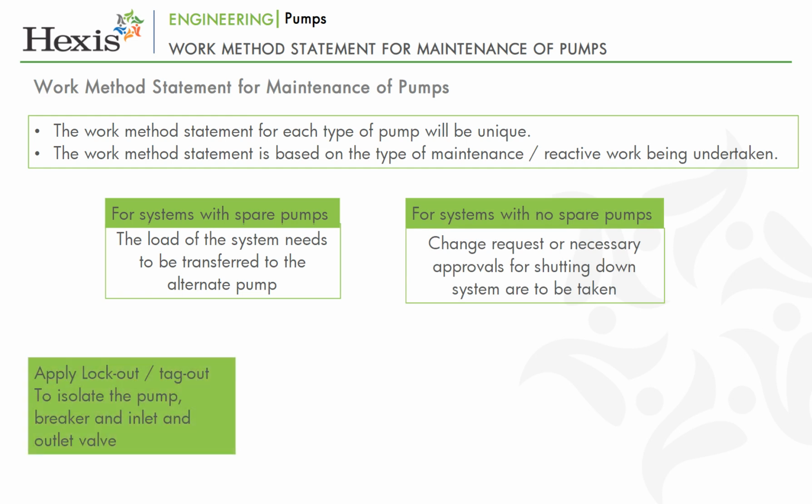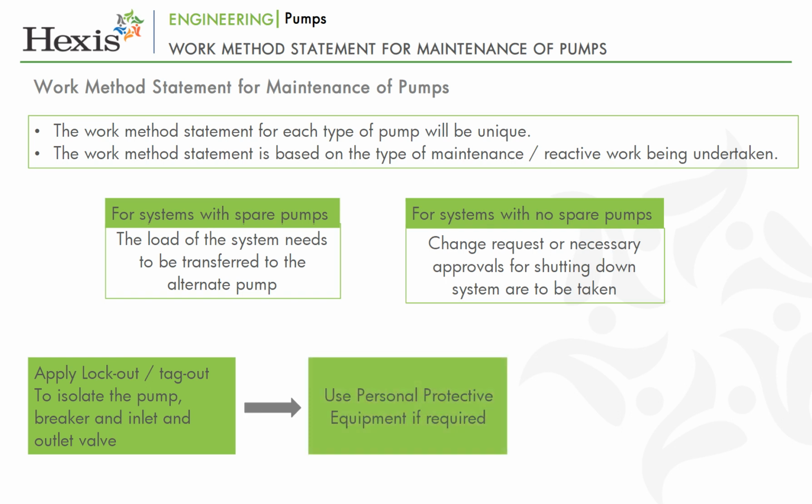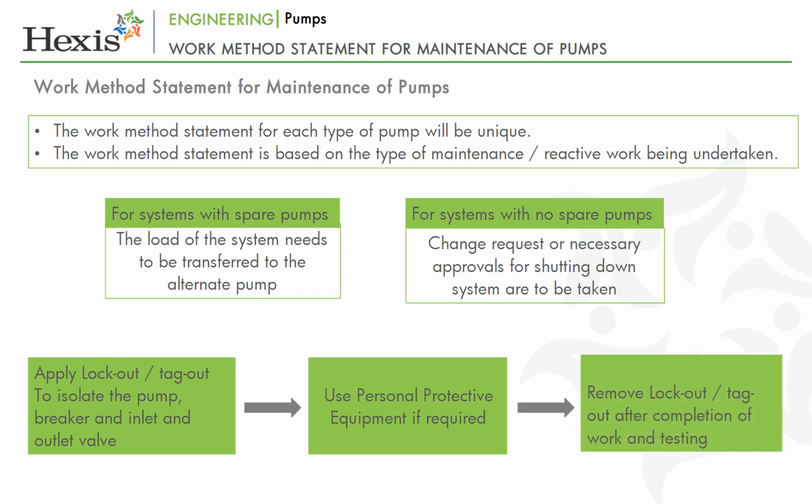Lockout or tagout needs to be applied for isolating the pump, electrically, that is breaker, and mechanically, that is inlet and outlet valve. Personal protective equipment, that is PPE, is to be used as required. Lockout or tagout is to be removed after completion of work and testing.